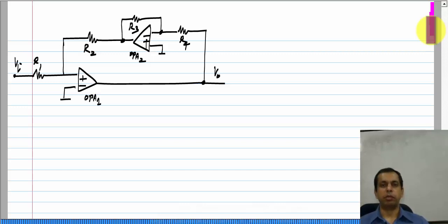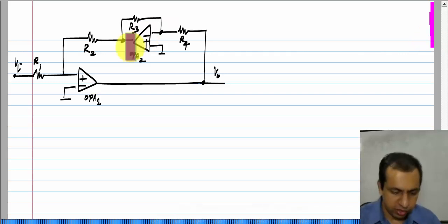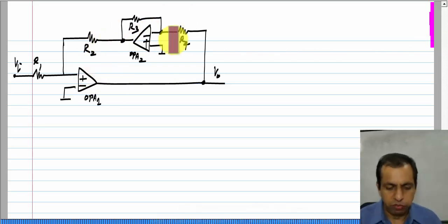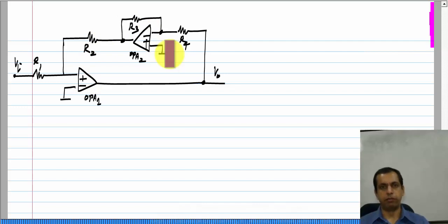And finally, sometimes you may have to resort to trial and error, because the op amp which you are replacing with the voltage controlled voltage source, you may not have determined its sign already. Okay. So, you have to consider both signs and then proceed, but eventually there will be a unique solution. You cannot have different possibilities, right. For this circuit, for instance, this is the only possibility. So, if you reverse the signs of both op amps, you will find that one of the op amps will be in positive feedback. Okay. So, that is the algorithm in short, and you can use this for any circuit with multiple op amps. Okay.